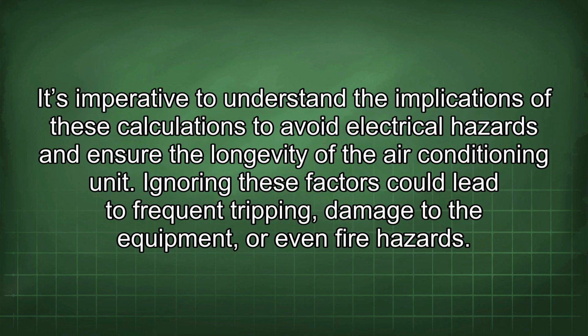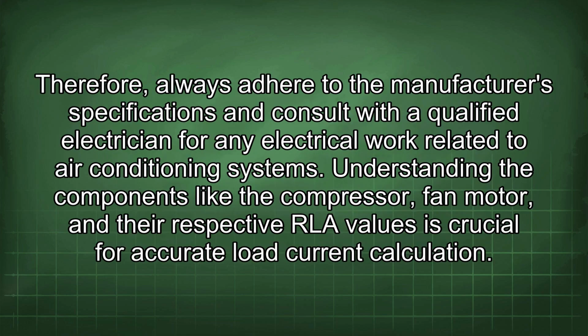It's imperative to understand the implications of these calculations to avoid electrical hazards and ensure the longevity of the air conditioning unit. Ignoring these factors could lead to frequent tripping, damage to the equipment, or even fire hazards. Therefore, always adhere to the manufacturer's specifications and consult with a qualified electrician for any electrical work related to air conditioning systems. Understanding the components like the compressor, fan motor, and their respective RLA values is crucial for accurate load